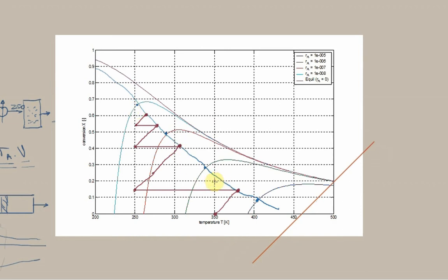Another rule of thumb that has crept in is that we could identify how far we want to stay from the undesirable region. So we know the undesirable region is this equilibrium point where, on balance, nothing is happening. So we could say, well, we can't reach that point because we know that's a zero. We'd need an infinitely large reactor to get there. But a simple rule of thumb is just to stay 10 degrees short of that line.